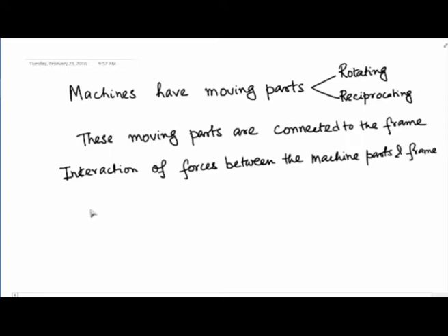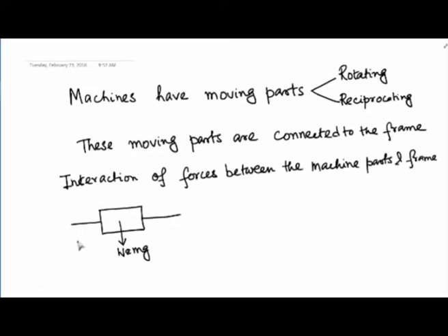And as per the example that is shown, if I have to draw that again, so this is my rotor shaft system. Obviously the rotor has some force, so this is the weight which is equal to mg of this component. To balance this weight, the bearing has to put in certain reactions, and let us say it is symmetrically arranged, so therefore the bearing has to put in an amount of force which is W by 2 and W by 2 at both the ends.